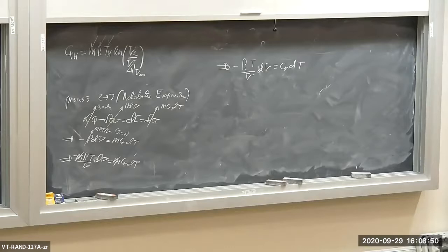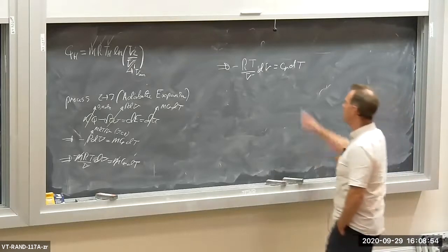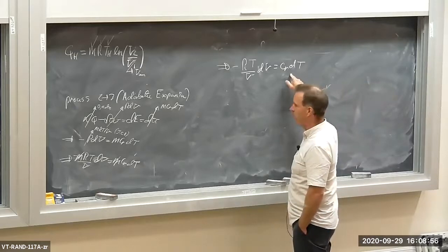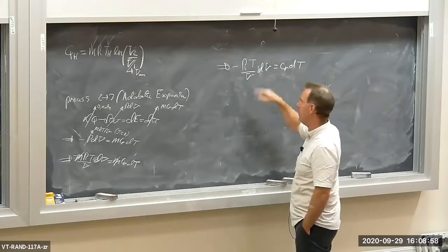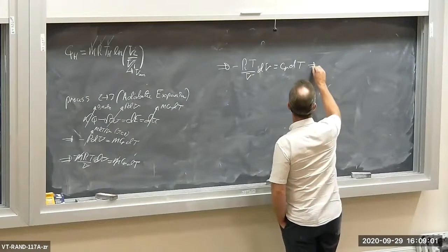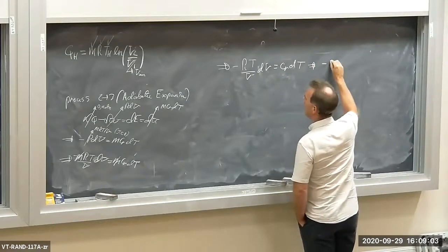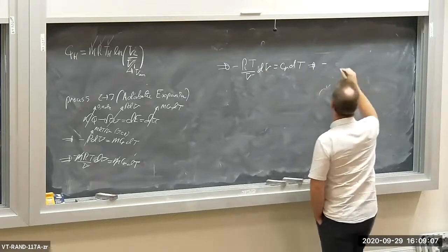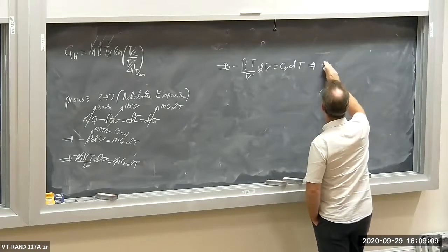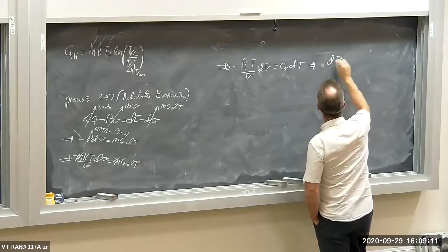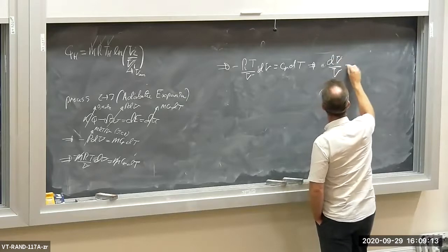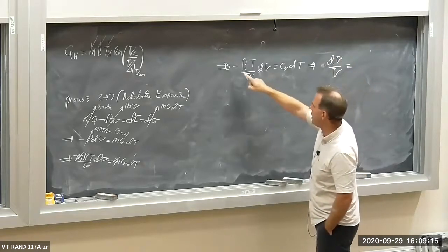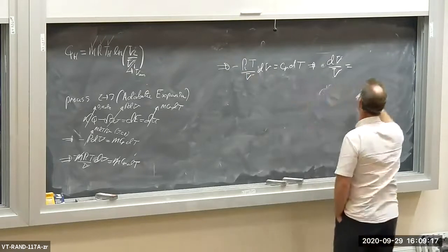I'm going to separate variables here and I'm going to integrate. I'm going to take all the temperatures and put them over on the right and leave the volumes on the left. I'm also going to take this R and put it over on the other side of the equation. So I got dV over V. Keep the dV and the V and put the negative RT over on the other side of the equation.